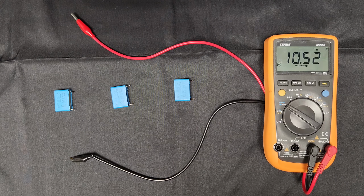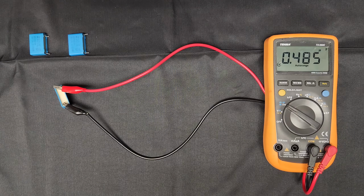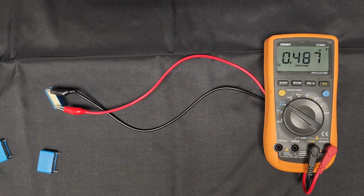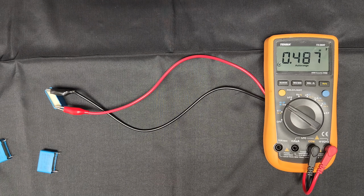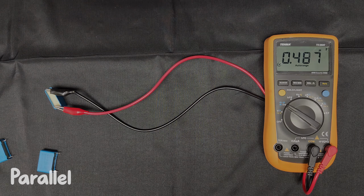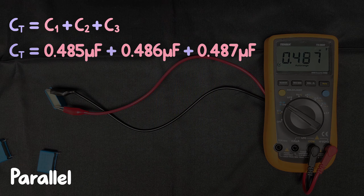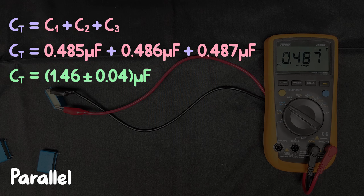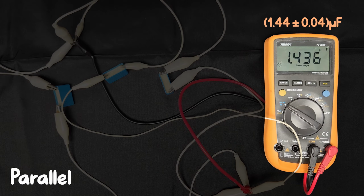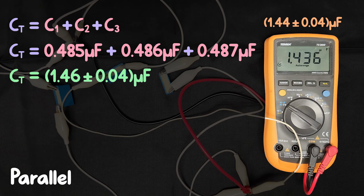I have here 3 capacitors with individual capacitances of 0.485, 0.486, and 0.487 microfarads. The multimeter used measures capacitance in this range with an uncertainty of 3%. When combined in parallel, capacitances add together, which would give a capacitance of 1.46 plus or minus 0.04 microfarads. Doing this practically, we get 1.44 plus or minus 0.04 microfarads, agreeing within uncertainty.